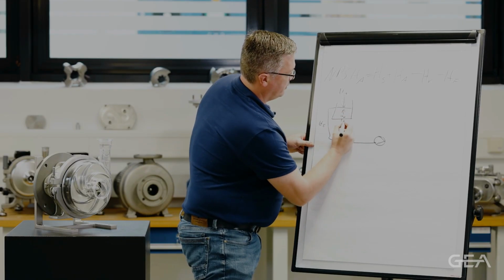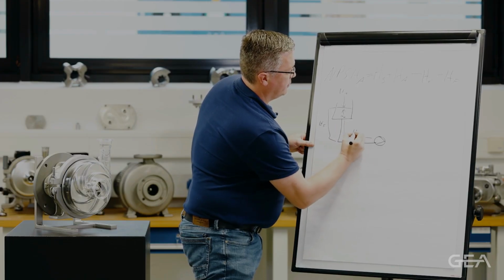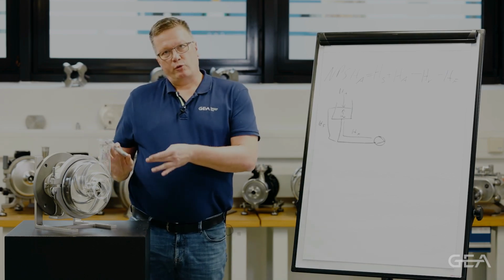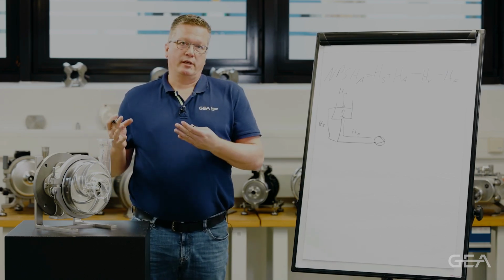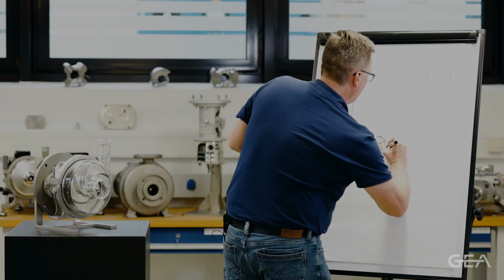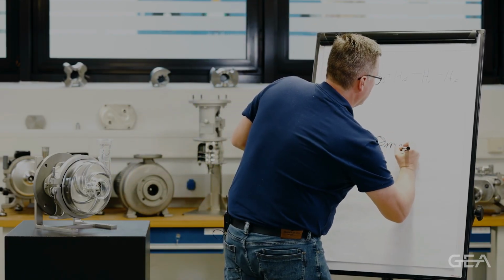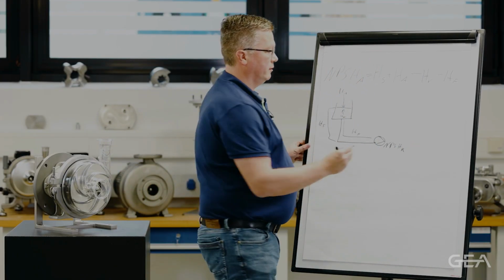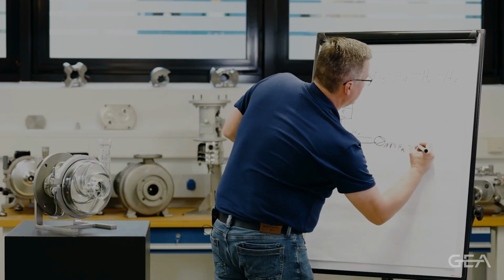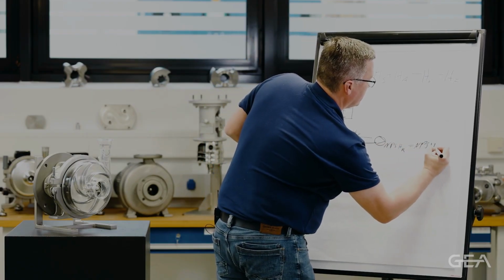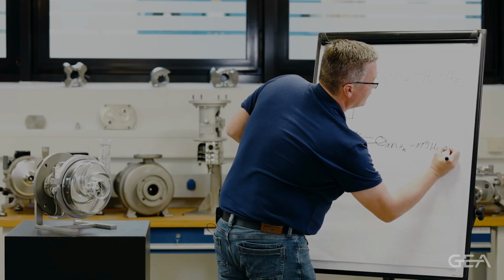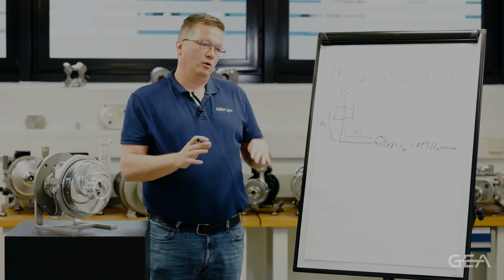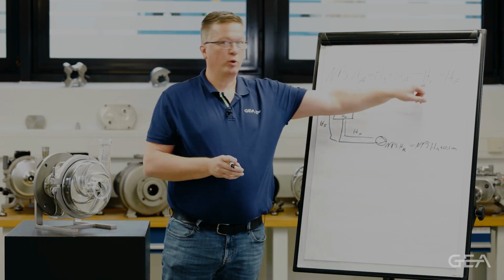And you have the friction losses that lower your NPSH. The pump now also requires a certain NPSH, which is NPSH required. And to have a safety factor, NPSH required is always available plus 0.5 meter, because we have some factors that are always changing, like the vapor pressure, for example.